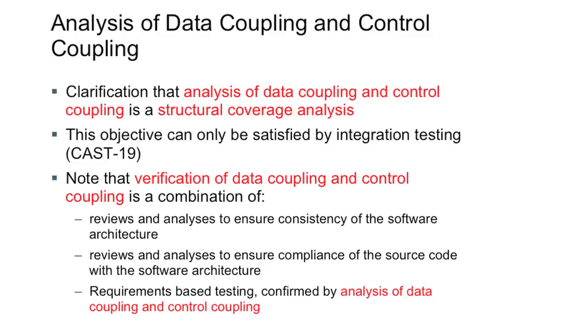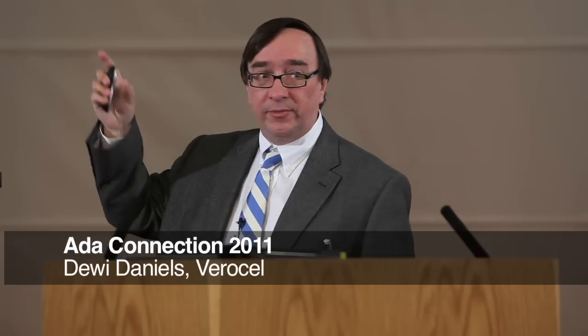There's this objective called analysis of data coupling and control coupling, which is probably the least understood objective in DO-178B. So in both DO-178C and DO-248C, we've tried to explain what that objective means. And it's basically an objective that can only be satisfied by integration testing.